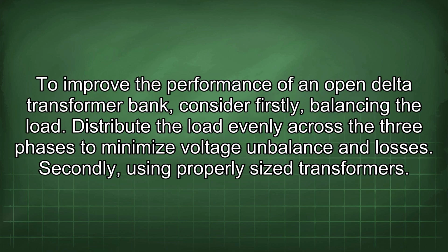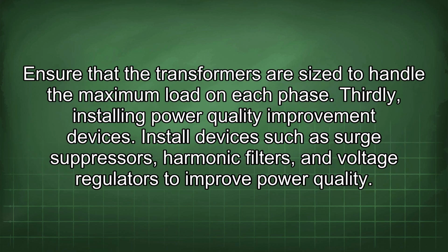To improve the performance of an open delta transformer bank, consider, firstly, balancing the load. Distribute the load evenly across the 3 phases to minimize voltage imbalance and losses. Secondly, using properly sized transformers. Ensure that the transformers are sized to handle the maximum load on each phase.